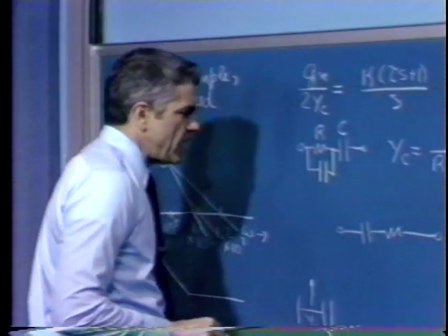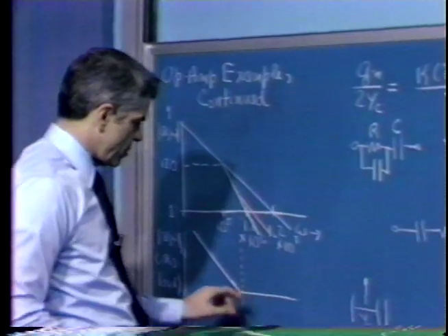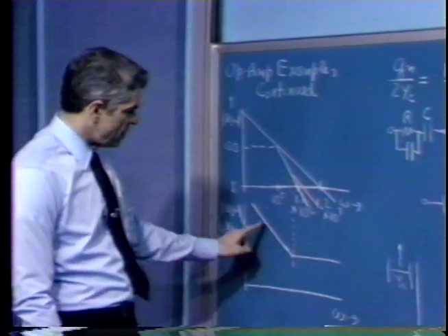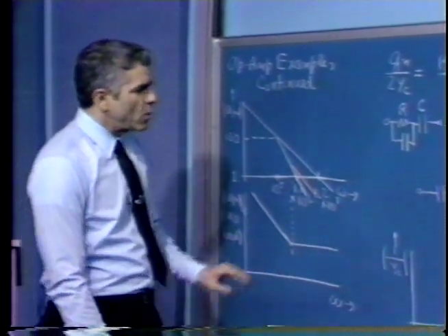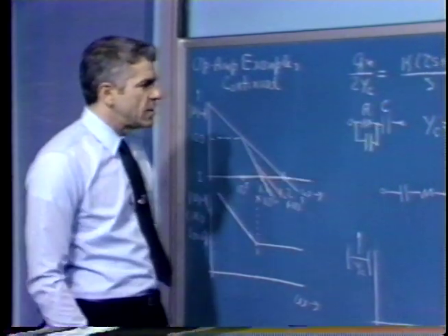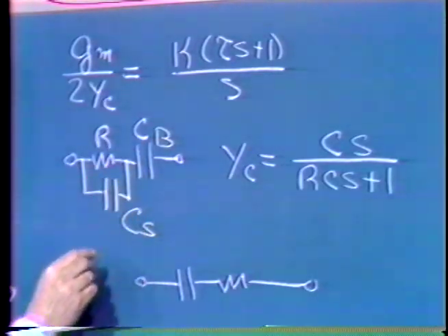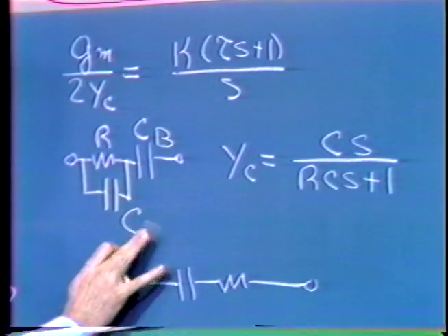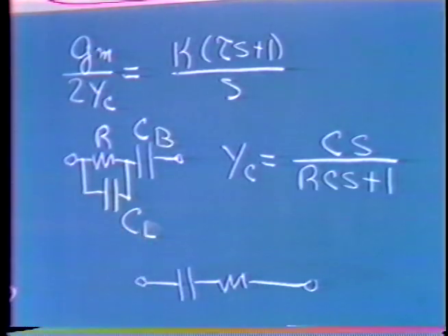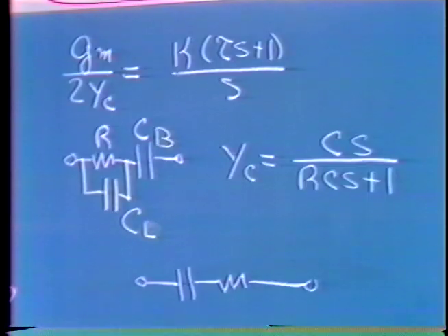Now, what we'd like to do is maintain the general feature associated with the transfer function we had mentioned earlier. And what that means is that this capacitor must be much smaller than our original capacitor. So we might call this some big capacitor, and this some small, or S is probably a poor choice, C little. And the ratio between C big and C little should be quite great.